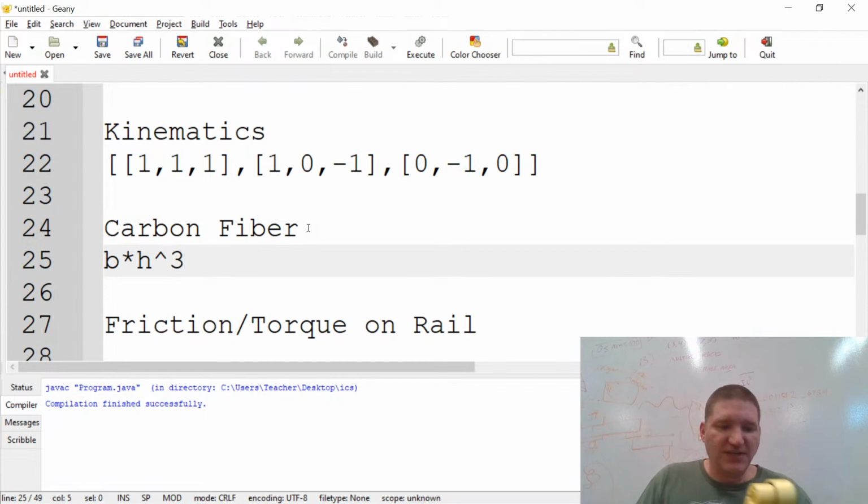I'm printing with PLA, which, by the way, of PET, ABS, all that stuff, PLA is actually the one that has the highest Young's modulus, so it's actually going to do the best. That's why I'm printing with PLA, and it smells good, and I have a lot of it. If they're suggesting I go to carbon fiber, I might increase the strength a little bit, but I could just take a humble approach and increase the dimension, and I can increase it a lot more than with carbon fiber, and I save a lot of money.